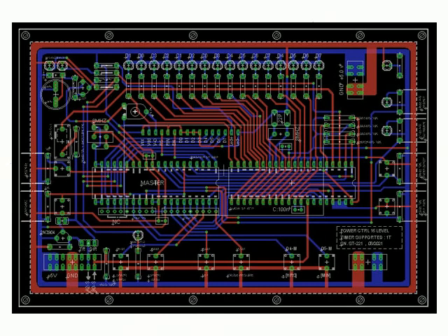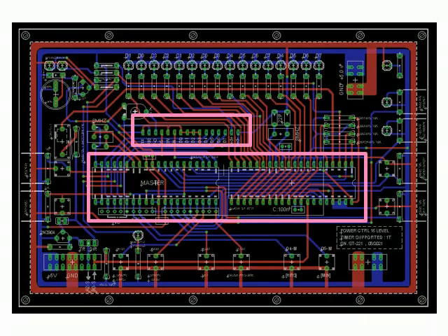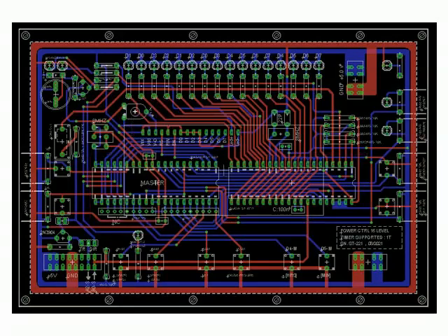The second part contains mainly the electronic microcontrollers and an LCD screen to display the data. This circuit controls the device's power within 16 levels, from 10% to 100%, with an increment step of 6%. The current power level is shown digitally on the screen, and visually on 16 LEDs at the front of the board. In addition to the power control process, an optional timer is also supported in the circuit, that can be easily adjusted, to automatically disconnect the device after a specified operating period, up to 24 hours.